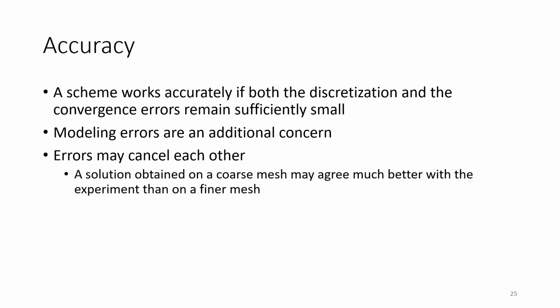It can be because I need fewer iterations and my convergence error is so much larger than my discretization error. So a coarser mesh might be better because I have maybe a larger discretization error, but the convergence error is decreasing so much. You see how things influence each other? So this is very difficult to answer in a general sense. But accuracy is, next to stability, one of those crucial numerical parameters that matters for any kind of numerical model.